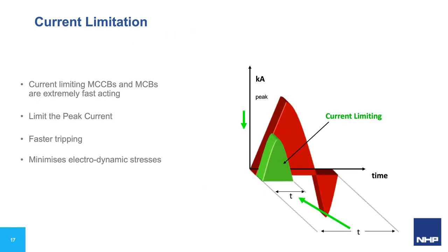As the two breakers acting in unison create the conditions where the current is limited in magnitude and the duration of the entire interruption process is shortened in total clearing time, the peak current may be limited and the let-through energy is lessened by the shortening of the current flow duration and the peak of the current value. This action minimizes the mechanical and heat stresses on the conductors in the circuit.